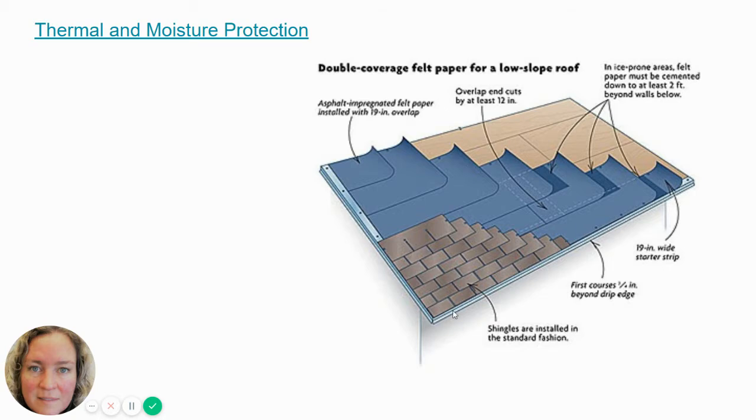And then this is how your shingles, these are called 3-tab or asphalt shingles, because you got 1, 2, 3 shingles, and a sheet can go down and you'll lay 3 shingles at a time. The first layer is always 2 layers of shingles. You can see there's 2 layers here, and then you start your coursing from there on. The reveal, or exposure, is the amount of shingle exposed for each layer. And these are great for medium to high sloped roofs.